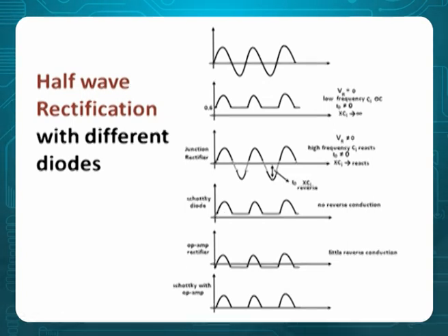Normally in the labs, when you look at low frequency, that's why you don't see conduction in the reverse direction. But at high frequency, junction capacitance comes into the picture, and accordingly conduction comes into the picture. Therefore, you cannot use it as a rectifier, whereas a Schottky diode is good to use because the cut-in voltage is less, and it is not affected even by high frequency. Capacitance may be there, but I naught is not there, so it doesn't conduct.